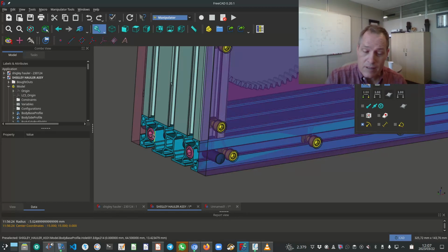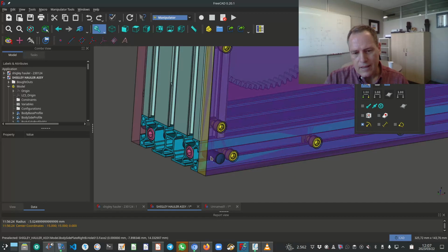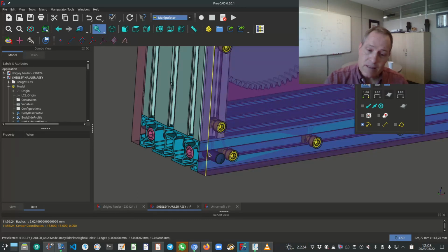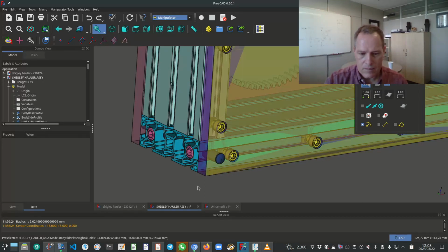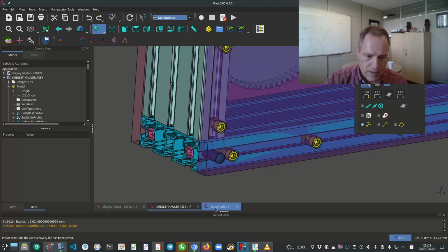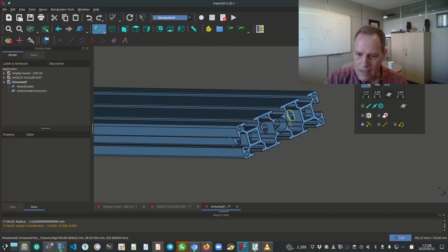The newer revision of the assembly has a single tapped hole here in the middle. This is the one that you've dimensioned now. So it's a slight change in the design, but the functioning is exactly the same. The idea is for these grub screws to clamp the dowel so that it is secured in the hole. It can't fall out. It can't move in and out of that hole. The design was slightly changed.